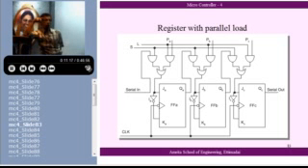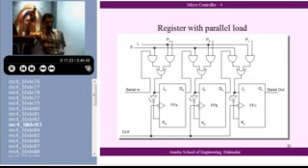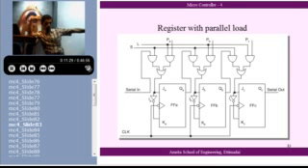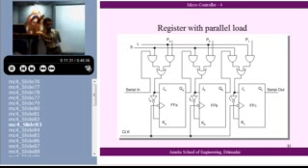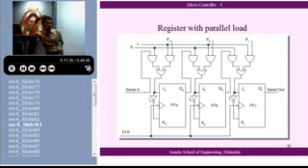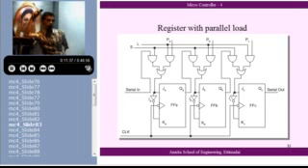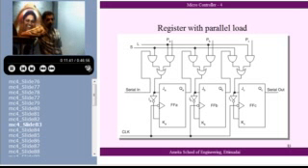So now it is a programmable device. The first step in the program is to do parallel loading. Remove loading, make L 0, make S high, give data. Where do you want to read? Now what I do, first I will make L high.